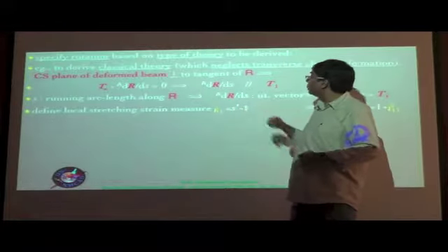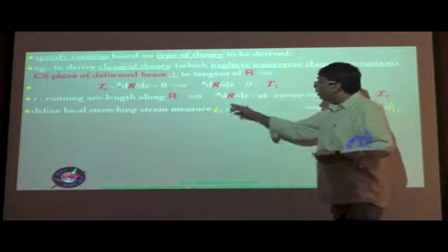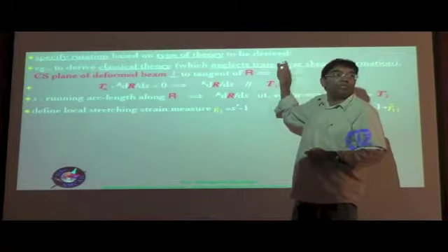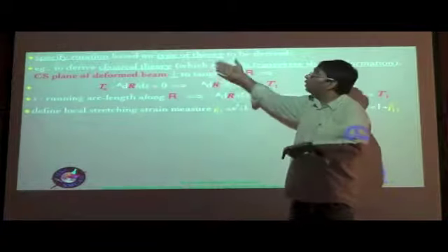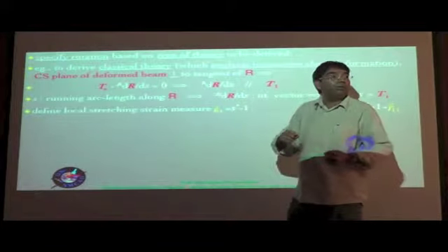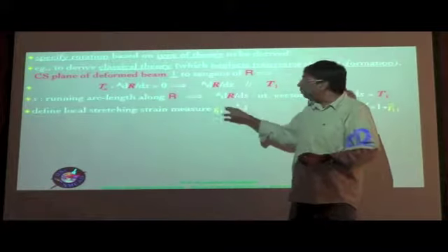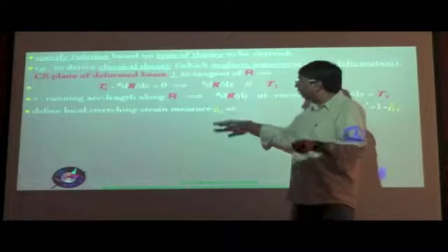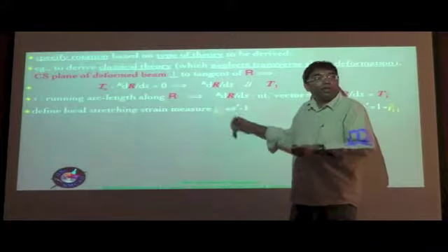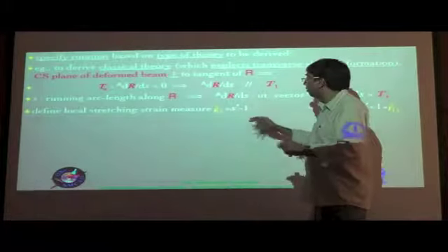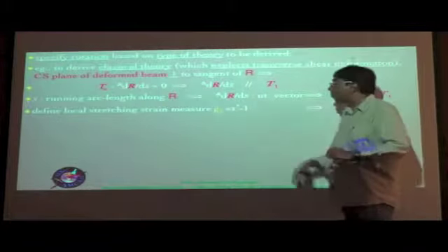So your gamma 11 bar is equal to S prime minus 1. This would not have been the case if we had not neglected the transverse shear deformation, or in the situation when we go to higher order approximation, when that transverse shear would automatically be captured by using the variational asymptotic method, you would see that this is not an exact relationship. Gamma 12 and gamma 13 would also contribute to a change in S in some way, but in a smaller way compared to gamma 11 bar. But this is the leading contribution to that.